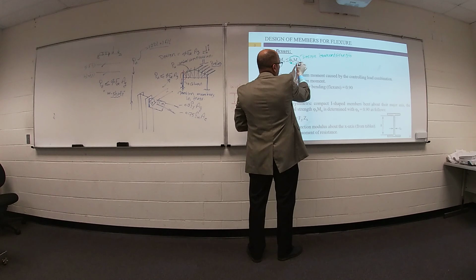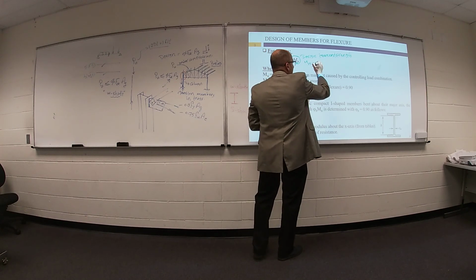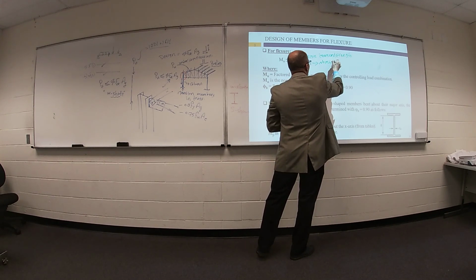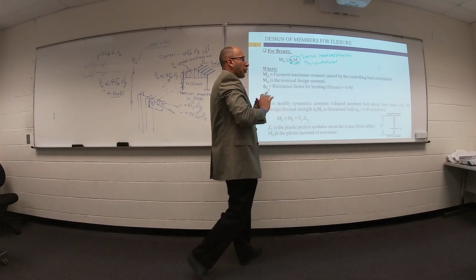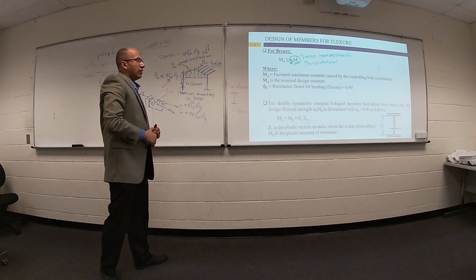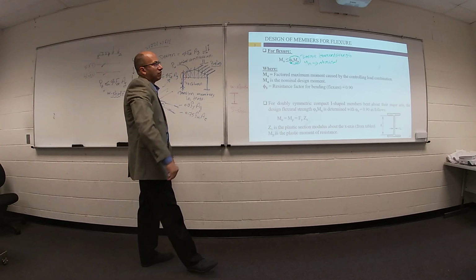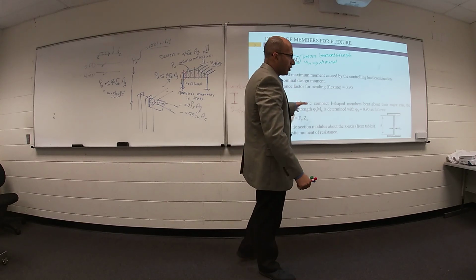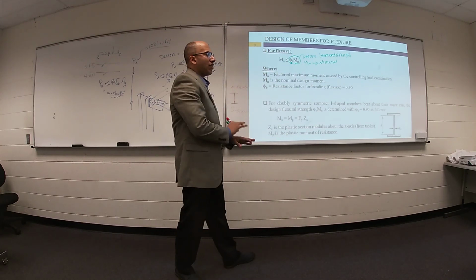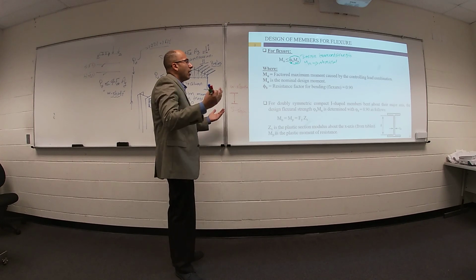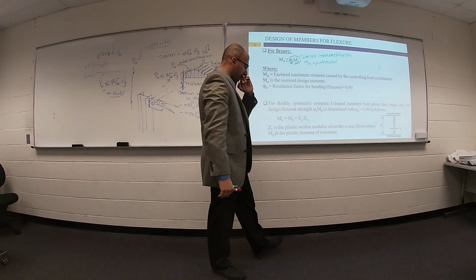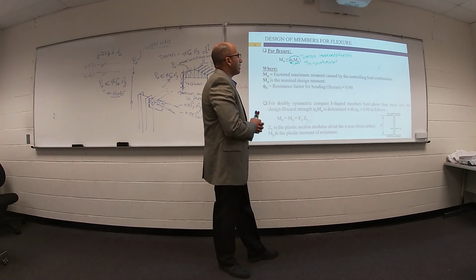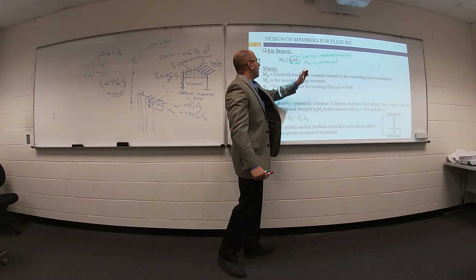without fail, your term Mn is called, anybody remember? Nominal. Nominal, yes. Nominal means without any factor of safety, theoretical. Actually, we need some factor of safety. As you see, the collapse happened in this bridge just after construction, without any use, with no live load, no moving load, just on the weight of the beam, collapse happened. So we need factor of safety.